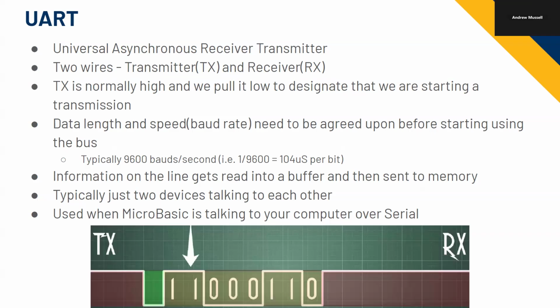So you're reading in the middle each time. Even if you have some jitter or skew and you drift one way or the other, you start in the middle, and it counts on the messages being short enough that even if I read here, then halfway, then towards the end, the messages aren't long enough that you could shift out and get an incorrect bit.